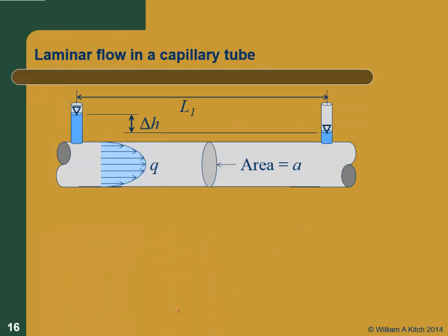Now, the flow at the flow rates that we're talking about in soils is always laminar flow. So the simplest model I could have of the pores would be tubes, right? I could imagine in a very simple model that the pores are just tubes. In that case, we got laminar flow, and if you remember laminar flow, we get this parabolic velocity gradient in a laminar flow area.